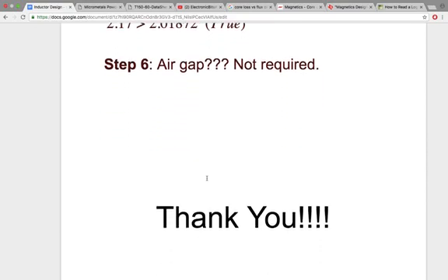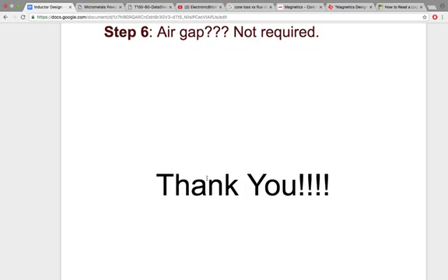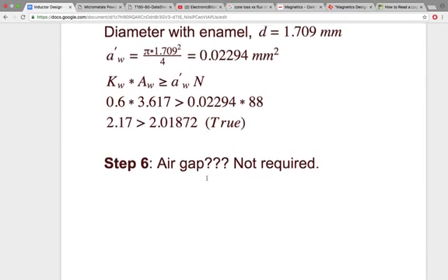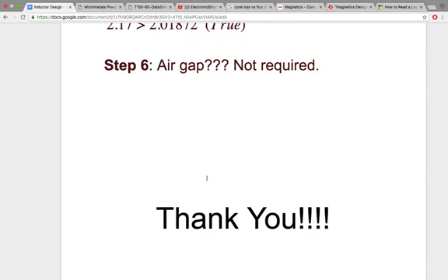So in conclusion, what we can say is there are two number-of-turns formulas. One has to check the AL inequality, and from there only we can decide which formula to go ahead with. And hence we have to verify whether we need an air gap or not. So basically the objective of this video was to answer that question correctly. Hence two examples were selected: one example tells that we need an air gap, and one example tells that we don't need an air gap, and the toroidal core is better.